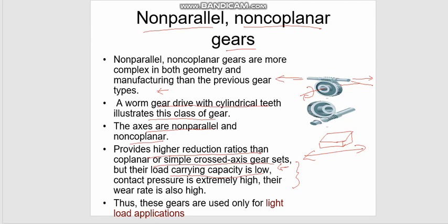So this is, let's say, where you mount the tools, and you want to move it along the x-axis. The way you move it along the axis is basically there's a wheel for you to rotate, right? So when you rotate the wheel, the tool holder assembly will move linearly left to right. So this is one of the common applications of such a gear system.